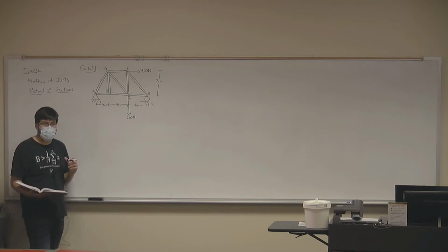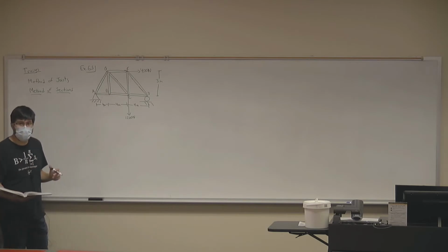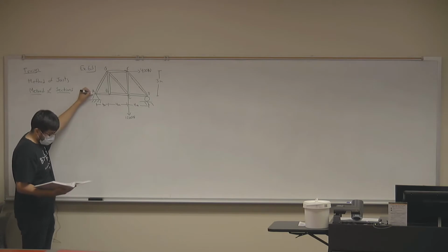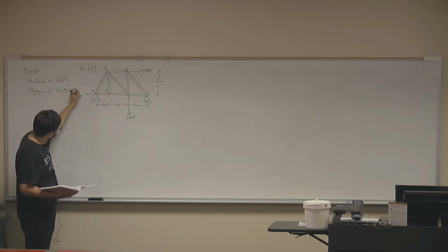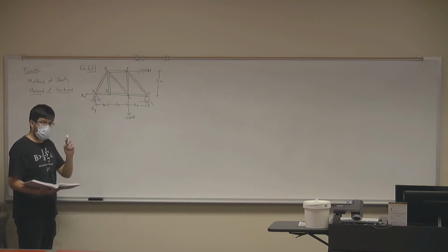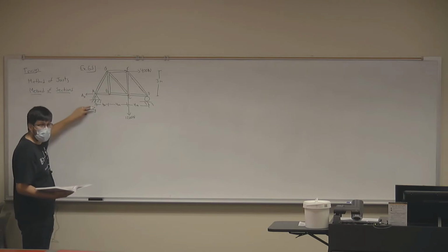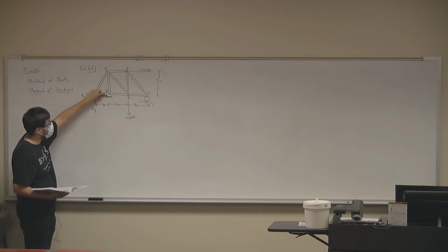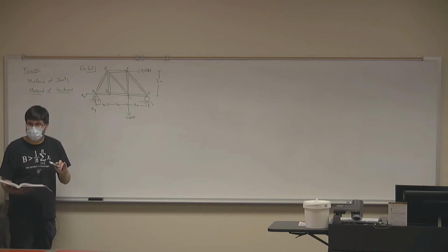3, 2, 7 moments. Just 3? 4? Okay, what are those forces, Lorenzo? There's the X reaction force. There's the Y reaction force. Then there's force AG and force AB. Exactly, right. A hinge gives you 2 reaction forces, AX, AY. But then you also have to consider the tension and compression of AG and AB. Is that correct? Does that make sense?